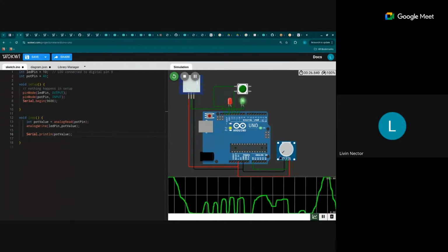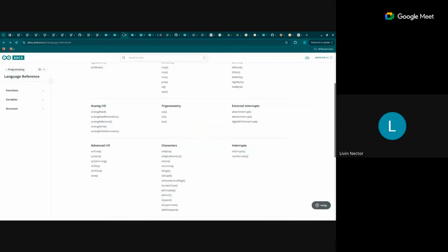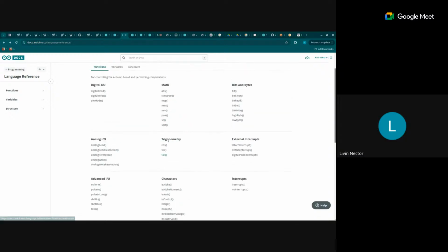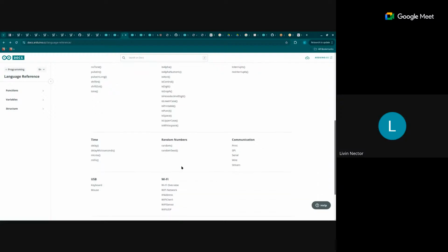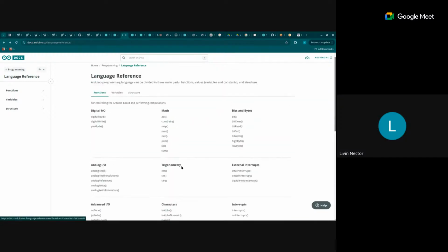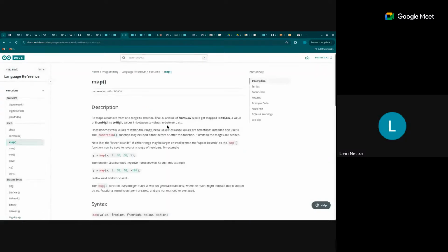But if you want to make that LED's brightness span the full range of the potentiometer, we want to do a mapping. So the mapping is like scaling of the inputs and outputs. For beginners, Arduino provides a very good convenience function just for that called map. So what this does is it converts one range of values to another range. That is the idea behind map.